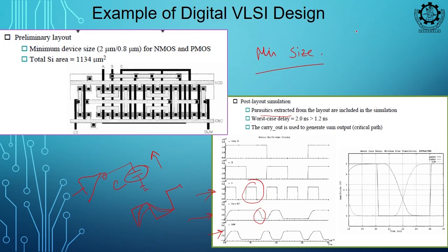We have a PMOS, right? We have an NMOS and we have a PMOS. Suppose this is W by L. What should be the size of the PMOS? Roughly 2.5 to 3 times, right? So, say 2.5 into W by L. You know why? I hope you know. Because mu n is roughly 2.5 to 3 times of mu p.